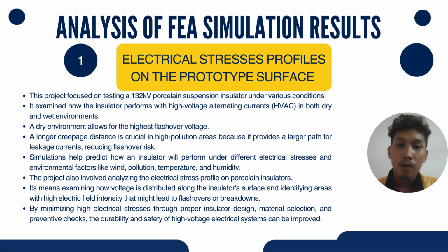The simulation helps predict how an insulator will perform under different electrical stresses and environmental factors like wind, pollution, temperature, and humidity. The project also involved analyzing the electrical stress profile on porcelain insulators. It means examining how voltage is distributed along the insulator surface and identifying areas with high electric field intensity that might lead to flashovers or breakdowns. By minimizing high electrical stress through proper insulator design, material selection, and preventive checks, the durability and safety of high voltage electrical systems can be improved.